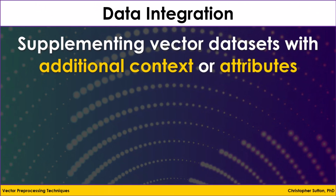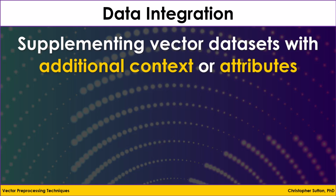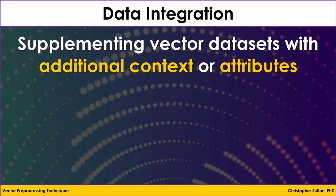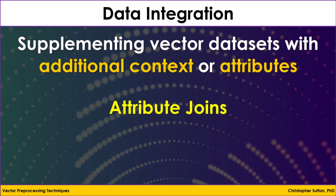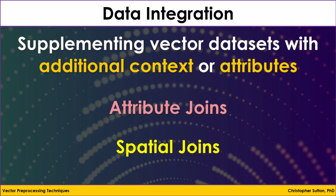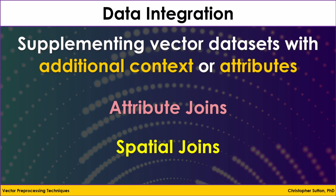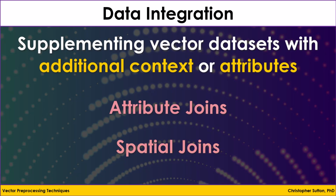There are several data integration techniques where we supplement vector datasets with additional context or attributes. Common ways of doing this include attribute joins, where we combine data from a table to a spatial layer using a common field, and spatial joins, where we transfer attributes between spatial layers based on locational relationships. I will discuss spatial joins in the next video.